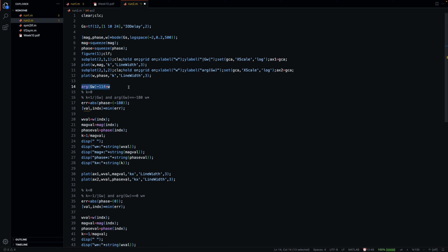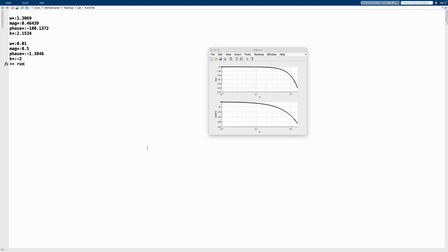So sometimes you're going to be given a Bode values table, and you might want to add another column, the system with delay, and then look for the omega value at that row, and then the argument of the system, and do this little calculation to update your Bode plot for different scenarios. What I mean by that is, if you have this taken out, and if you don't have this for a moment, you will see it will be a totally different story.